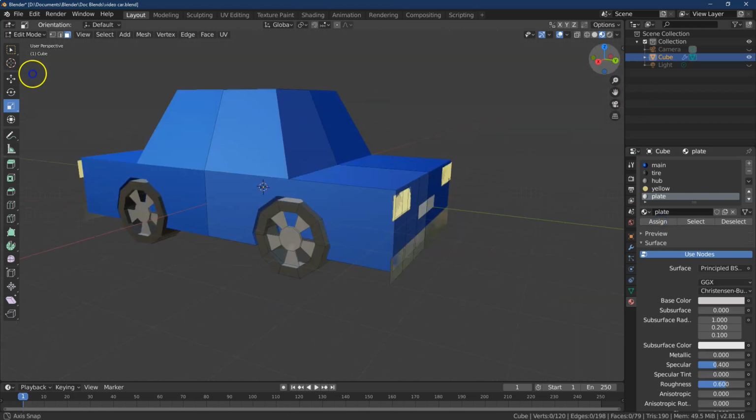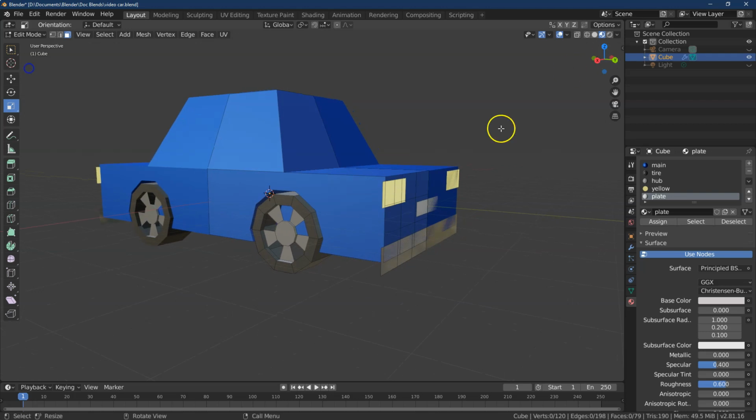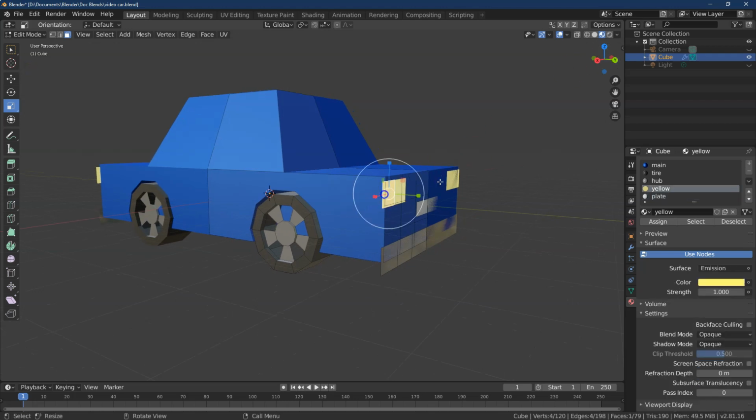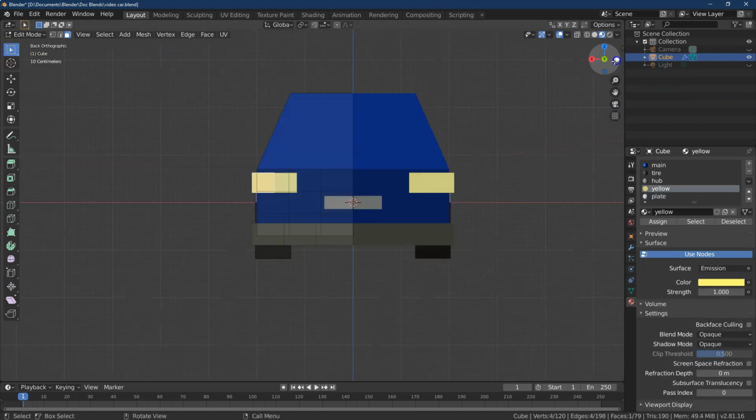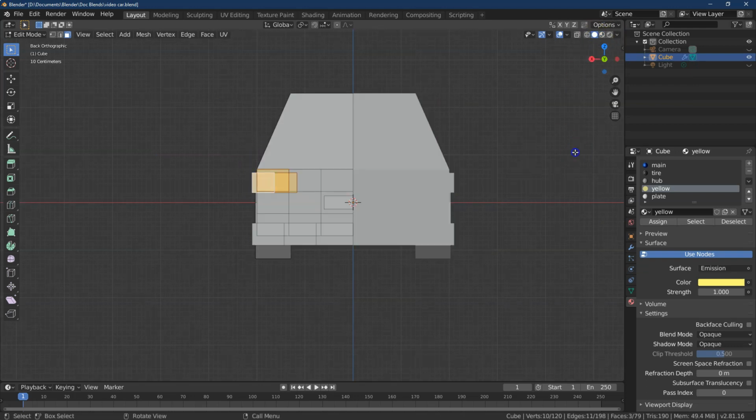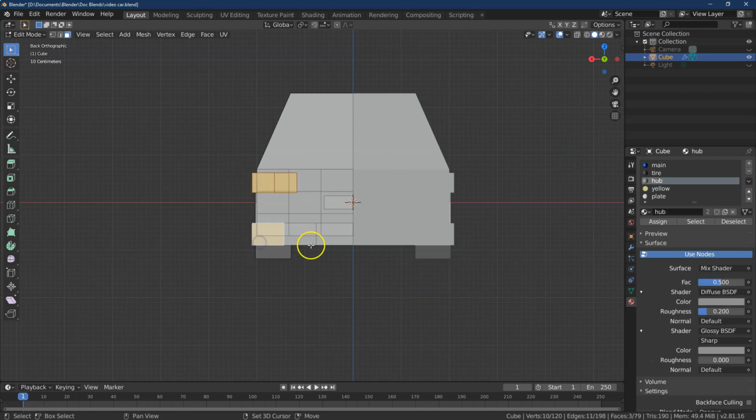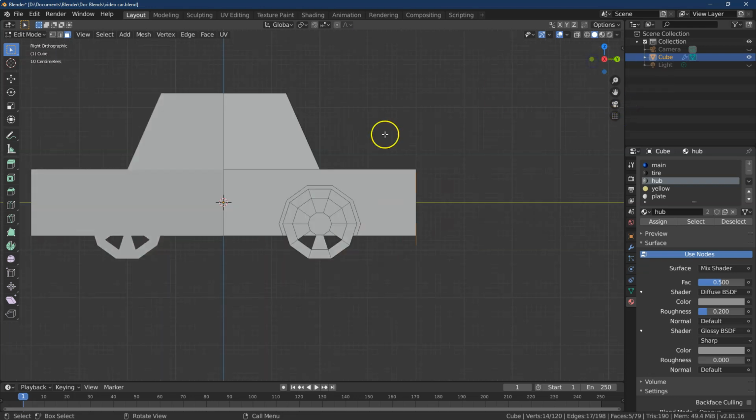Okay, so let's go ahead and start working on extruding these. Actually, let's take front view again. I'm holding shift, selecting this face and our bumper. Okay, I'm going to hit X, and now I'm going to go to extrude, and oops, I unclicked, undo, extrude, and then extrude along normals.